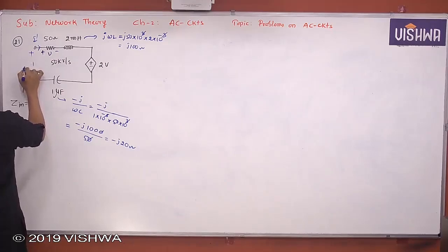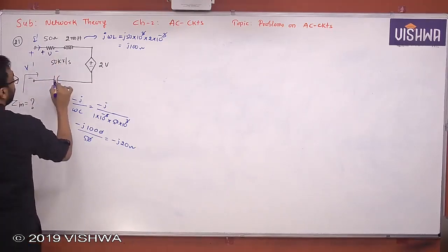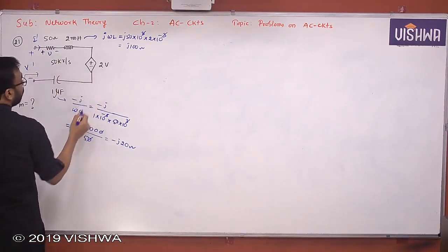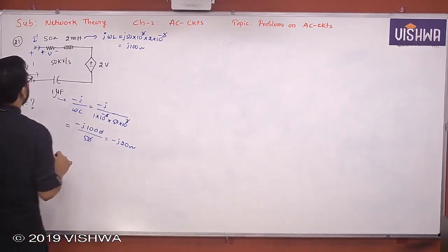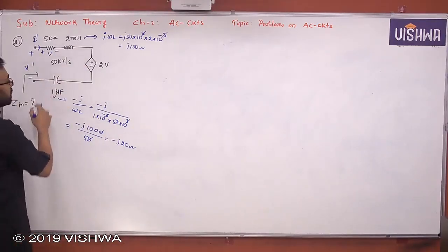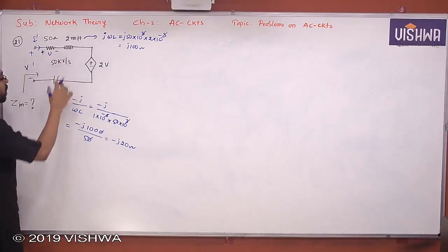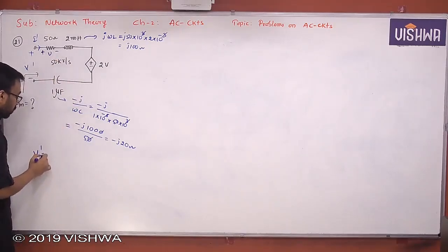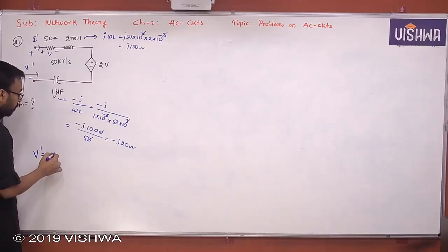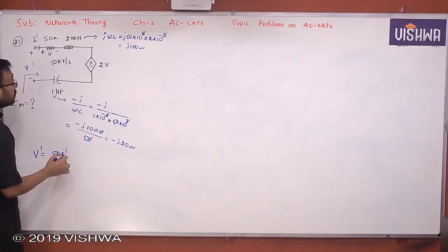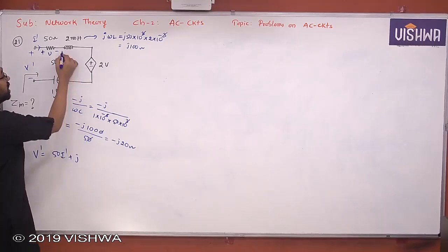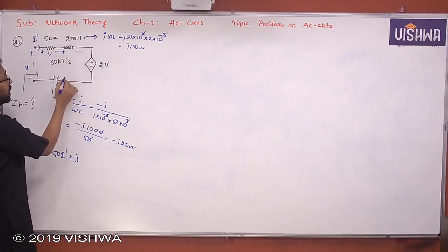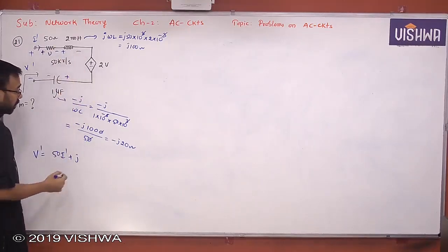So if you apply the Thevenin technique, say this is V dash, this is I dash, capital V. Now this is also capital V, V dash, and this also becomes capital V because we converted everything into complex. When you apply the technique, it's a single loop with a voltage source. Directly you can take V dash is equal to 50 I dash, I'm just using the touching concept, plus j100 I dash, because the polarities will become plus minus only. Here also this is plus minus. You're touching the positive sign first.